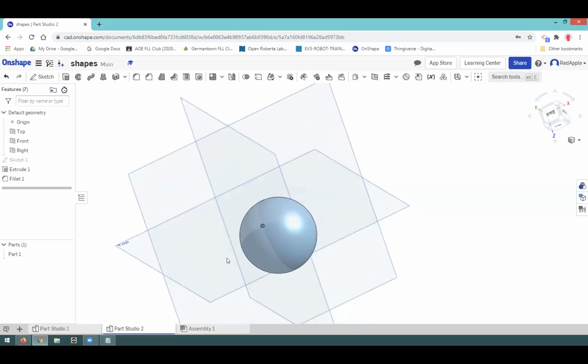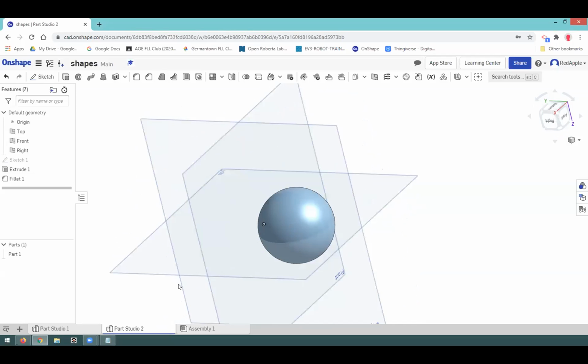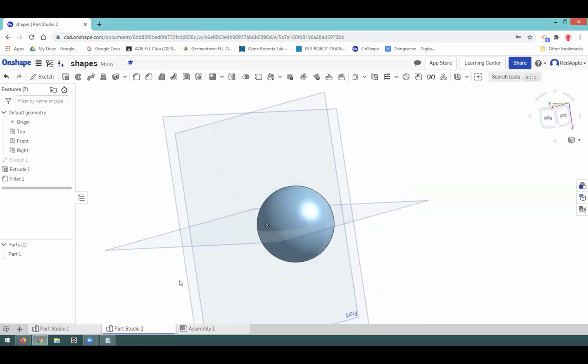Ah, nice. So he used one way to draw a sphere. He extruded the cube and used a fillet operation to cut off all the corners. Now there's another way to use what we learned today to draw a sphere, which is using revolve. See if you can think about that and draw a sphere using revolve. It's actually a one-step operation, and it should be a little easier.